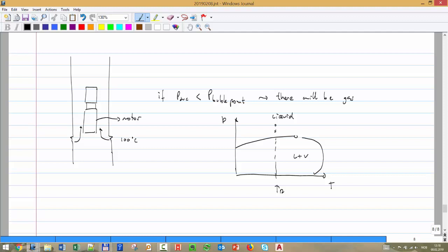If not, then you have to have this gas liquid separator. That means that you have a mixture, can be a mixture of oil and gas coming inside. Then you separate. You have another module here that's actually where the pump is. That's the pump. And the liquid continues inside through the pump, but the gas flows outside through the annulus.